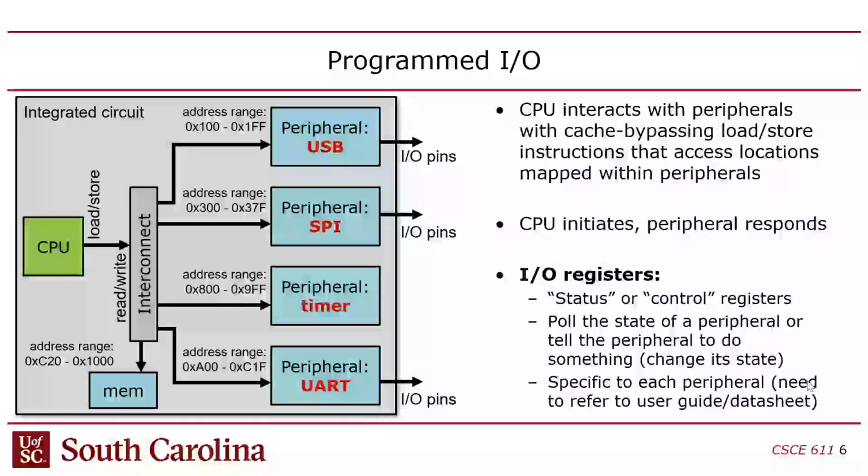That's why they call them... Now that terminology is a little out of date. No one calls them control and status registers anymore, it seems. It's still, but they're basically the same thing. The only difference is a control register is something you're supposed to write to, and a status register is something you're supposed to read from, right? So control is an output, status is an input.